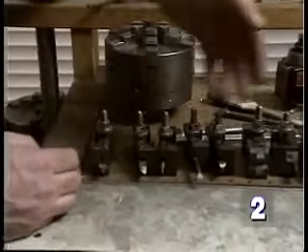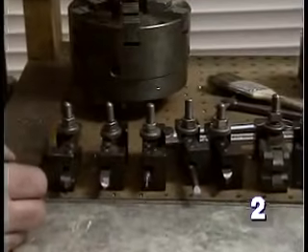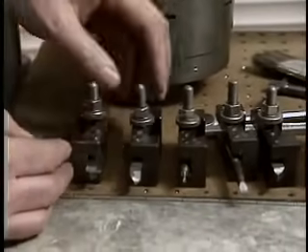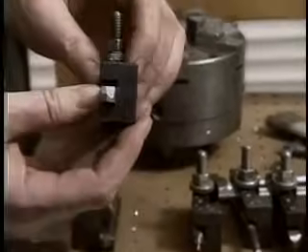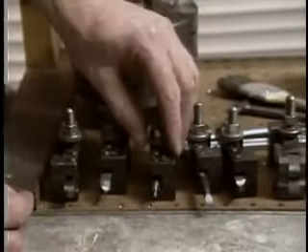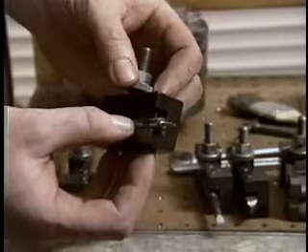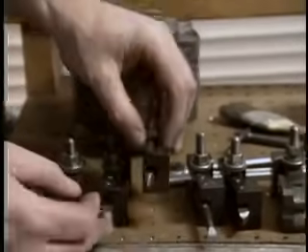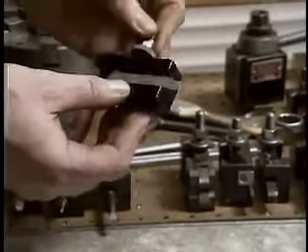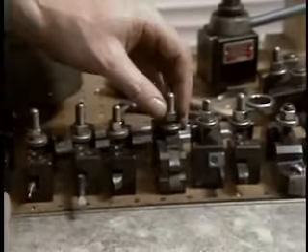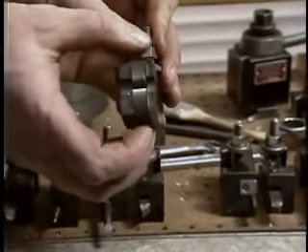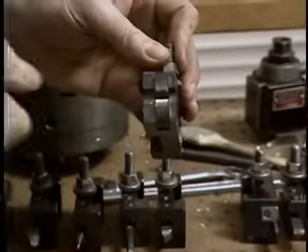What I have here is a typical array of tools for a prototype shop. We have the tool I showed you, which is a general purpose turning tool. Then a tool used for cutting plastic, cutting in this direction. Then we have a couple of boring tools. A very small boring tool for making very precise holes. Here's a larger boring tool. Another turning tool. This odd tool is for knurling, for roughening the surface of a part, typically so you can get a better grip on it.